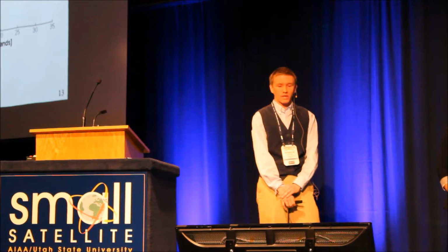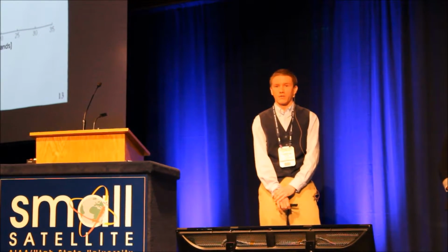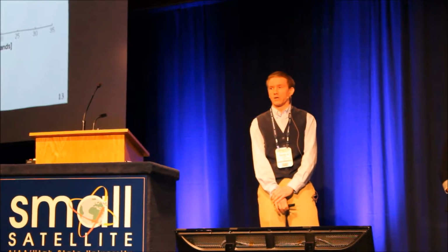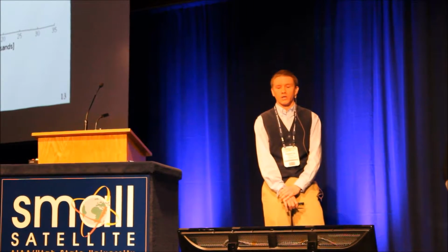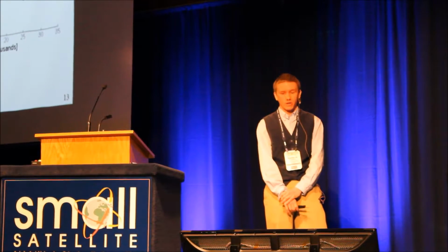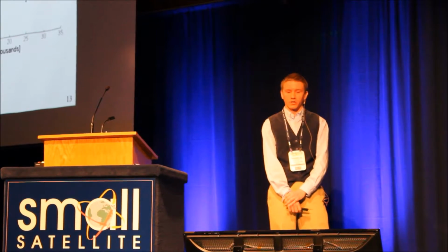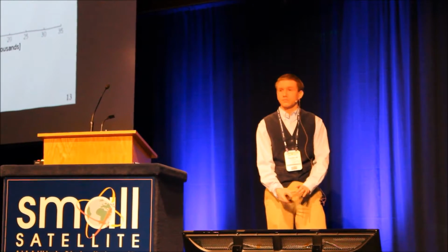Really, your main tool, we found, was to have a really robust and thorough safety mode. You have wide and diverse entry conditions to be able to handle many errors going into the mode, and try to have minimal functionality in that mode, particularly regarding power issues and the file generation issue we mentioned. Make sure you're not making those errors worse, so that theoretically you should be able to remain in the mode indefinitely. Next slide.